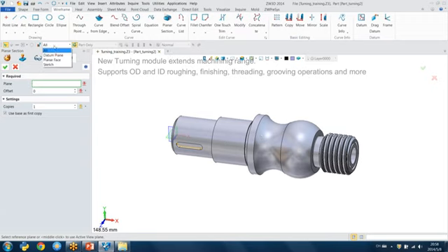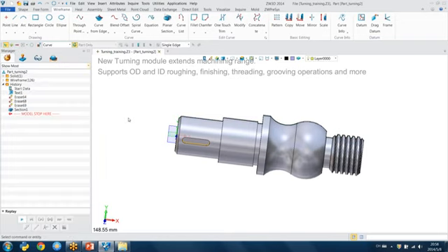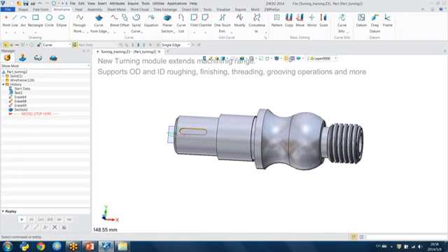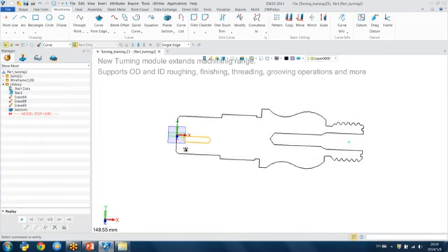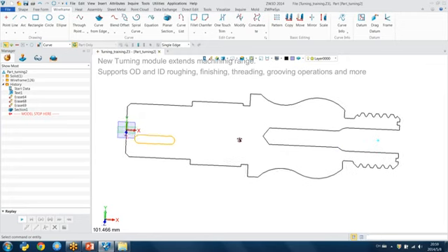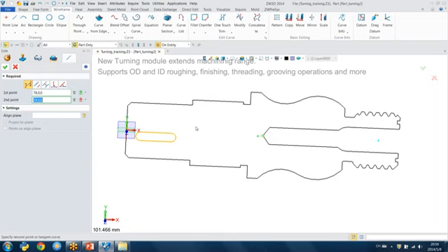So choose the shape, choose the plane. You must remember, choose the XY plane and set offset to 0 and press OK. And then you can find the blank shape. So I need to create the join a line to 0.